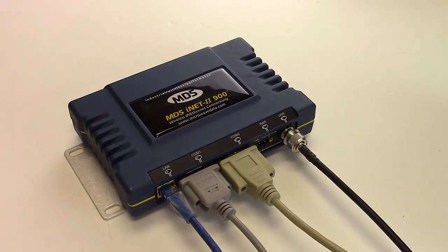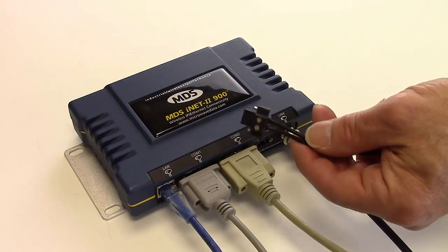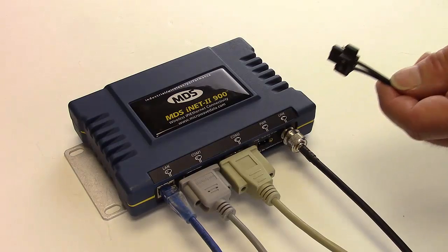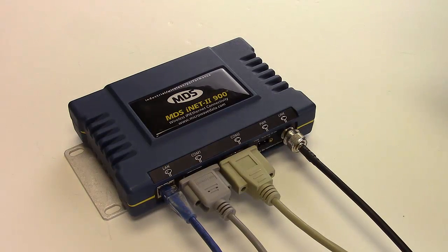With our cable connections made, it's time to connect the DC power to the radio. We save this for last because it's advisable to not have the radio transmitting without a proper antenna or RF load attached. Our power plug here has already been wired with the correct polarity and is ready for insertion. Always check the label above the radio's power socket for proper voltage and polarity.